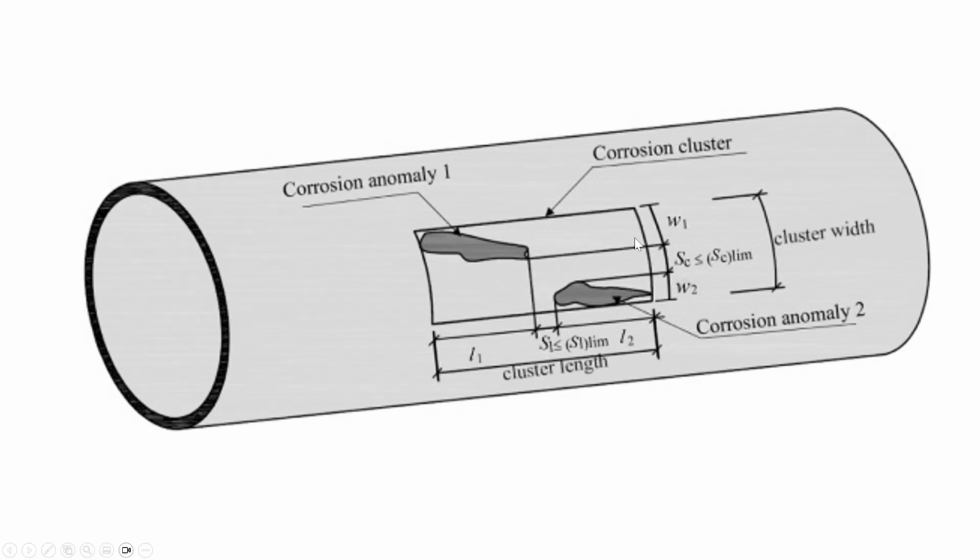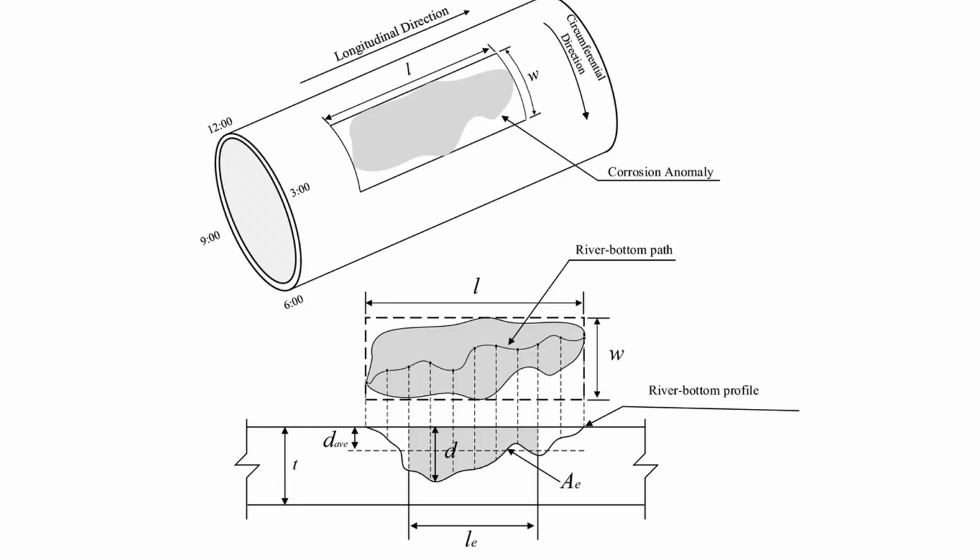And if it is clustering, you draw a big box across that area and look at that entire area instead for corrosion. And then you would apply a corrosion model. There's a ton of different models. The big one that we're going to show is called effective area, RSTRENG. It's a level 2 assessment that builds a grid across your pipe. We're building 1,000 different grids, and we're doing a factorial experiment to see the worst possible area combination, the one with the weakest burst pressure, and that's the model we provide.